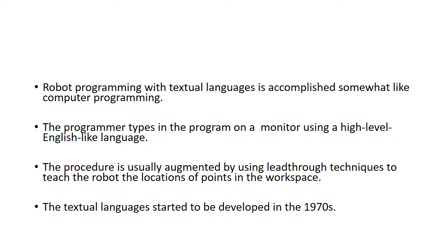Robot programming with textual languages is accomplished somewhat like computer programming. The programmer types in the program on a monitor using a high-level English-like language. The procedure is usually augmented by using lead-through techniques to teach the robot the locations of points in the workspace. The textual languages started to be developed in the 1970s.